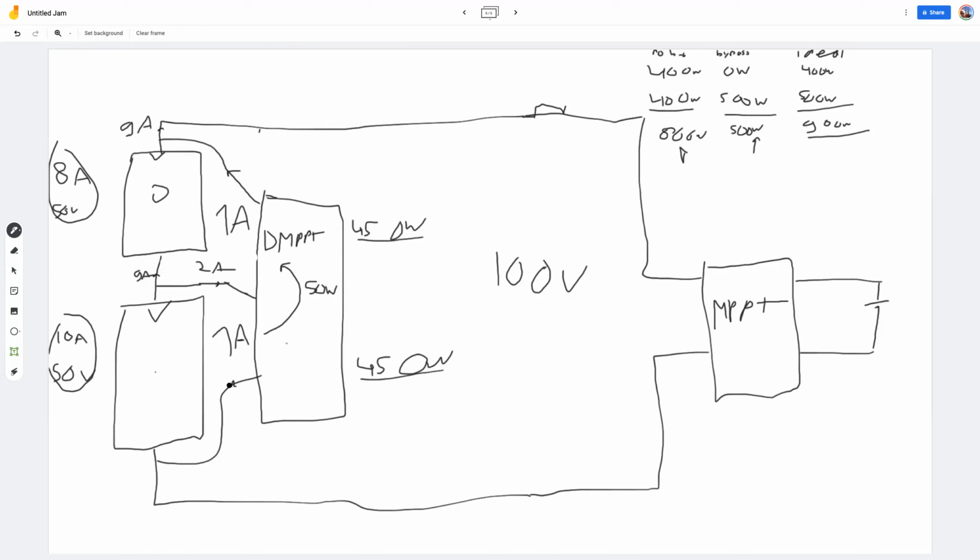Because this current flows like this. Let me get the arrows right. This is a donor, so the current goes like this to donate 1 amp. And this is a receiver, so the current goes into the cell, like this, 1 amp. So there's 1 amp floating like this, 1 amp floating like this. We basically have a box that has 2 amps here, 1 amp there, and 1 amp there. If we have terminals 1, 2, and 3, the voltage between terminal 1 and 2 is 50 volts because it's the same as the cell. The voltage between terminal 2 and 3 is 50 volts.